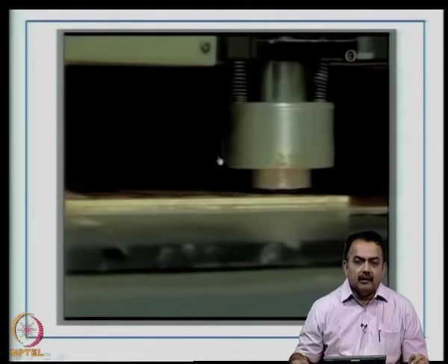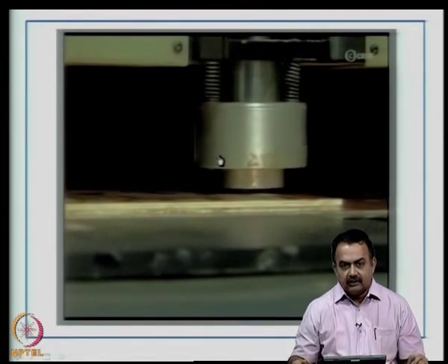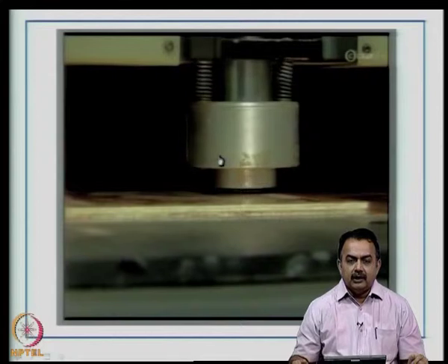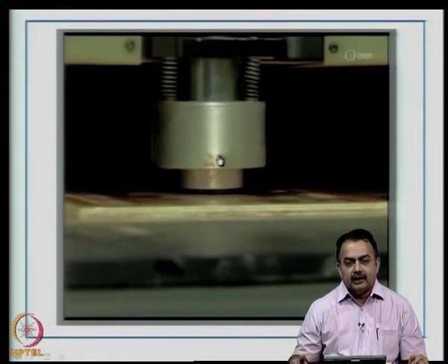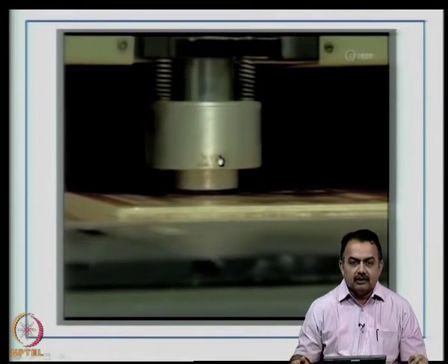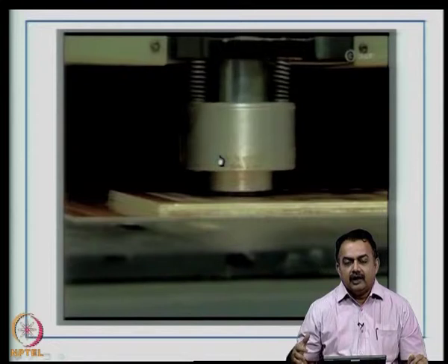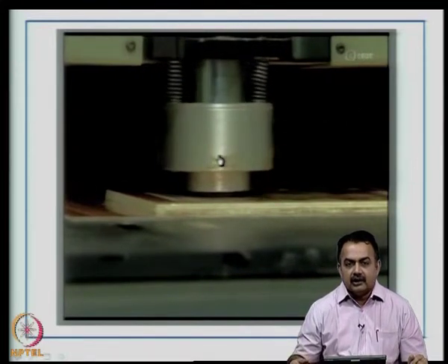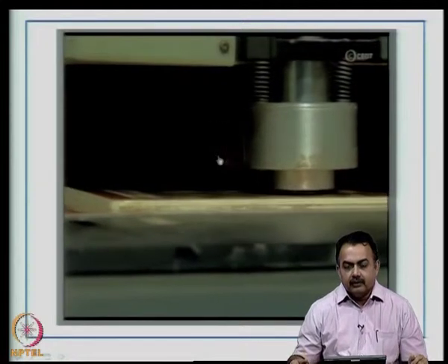In any CNC drilling machine, you will see that the debris are coming out or dispersed on the surface of the laminate, but they will be vacuum pulled into a collector close to the CNC drilling machine, so that the dust coming from the glass fabric and the organic resin does not spread throughout the machine and the adjoining areas.